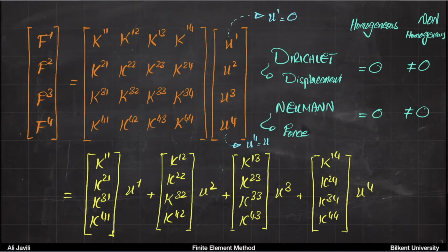So either you take something in your hand and you deform it, and then you just measure how much you deform it, and you don't know how much force you applied, but you can calculate the force. Or you have some sort of force gauge, or you apply a weight to it, so you know how much force it is, and then you can calculate the deformation. So the first one, where you apply displacement, is the so-called Dirichlet type boundary condition.